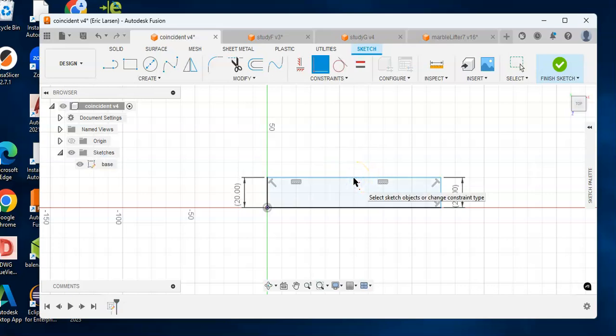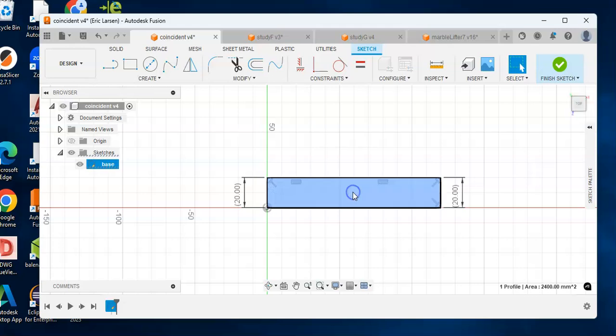If we click on it, wow, now it's fixed. It made those two points occupy the same space. Now we have a closed profile. We hit Escape, say we're done with it, and we can click here and get a closed profile, which we could not do before because it wasn't closed.